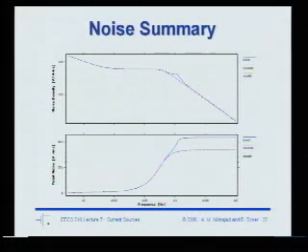And if you're using this in an application where you're picking up noise from all frequencies, like in a sampling system, this noise will hurt you. The penalty is not so bad. For this simple device, you're going from 35 microvolts RMS to about 40 microvolts RMS. But clearly, if you use more amplifying stages, you'd get an even higher penalty.